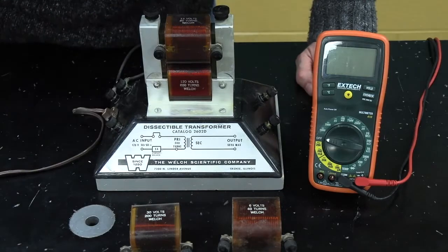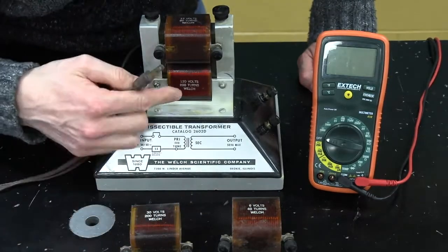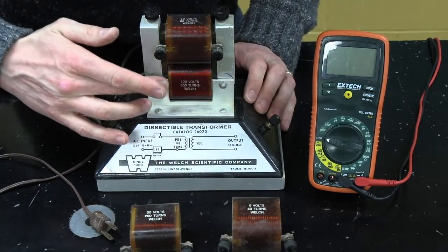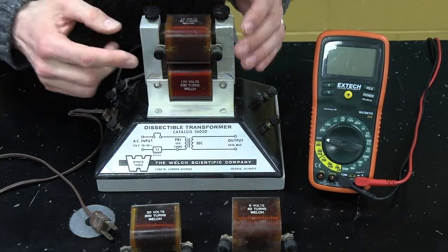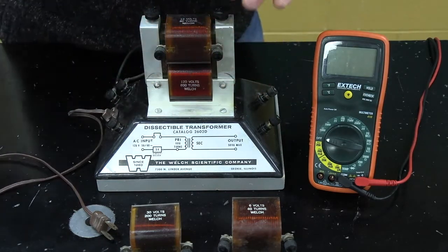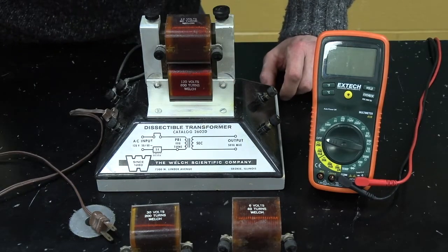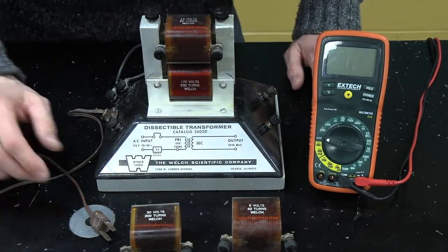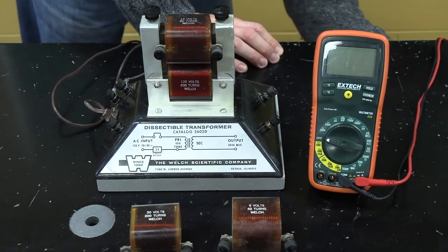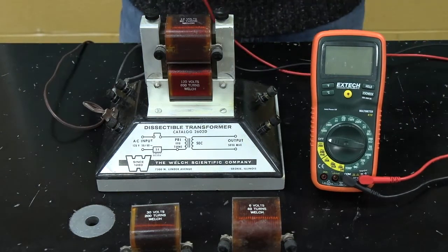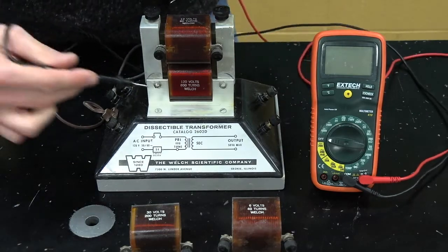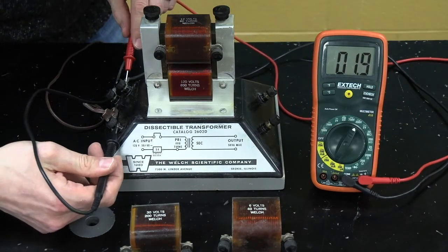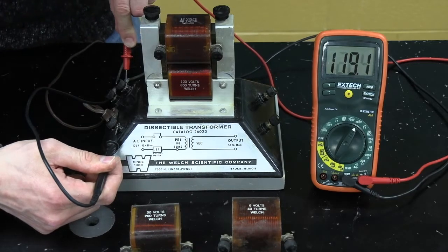Now, as this coil gets electricity from the wall at 120 volts and it oscillates back and forth in this coil, it's going to create an oscillating magnetic field that gets piped around and oscillates up here. But the difference in coils allows a different amount of magnetic flux changing, which will then create a different amount of voltage. I'm going to plug this in, and it's going to buzz a little bit because of the vibration, but basically I can measure the voltage coming into this primary coil with this multimeter, and if I touch over here, you'll see that coming in is 120 volts.